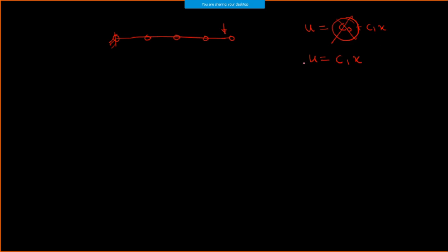What will happen with this? If I don't take c0 as a constant term into my polynomial itself, and I apply a force F here, then if I observe the displacement of this particular element, I will get a displacement of 0 here, and somewhere I'll get this displacement. This will have the same displacement because you are not going to apply any displacement. Actually, your displacement pattern looks like this if you are not taking a constant term.